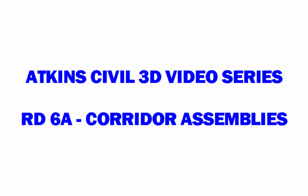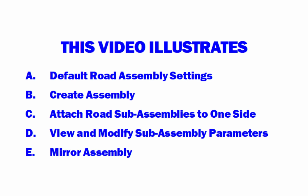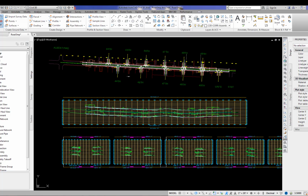Atkins Civil 3D video series, Road 6A, Corridor Assemblies. This video illustrates: A, default road assembly settings; B, create assembly; C, attach road sub-assemblies to one side; D, view and modify sub-assembly parameters; and E, mirror assembly. An assembly is a Civil 3D object that consists of several sub-assemblies that define the road cross-section at